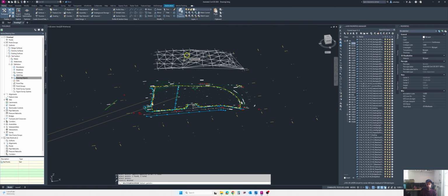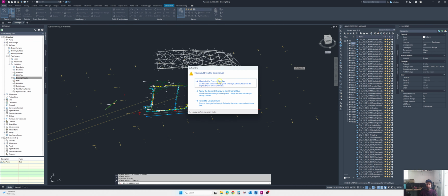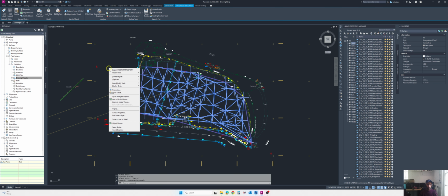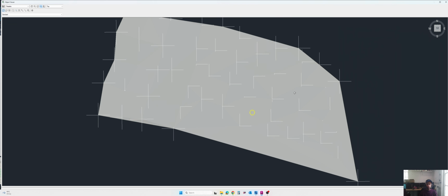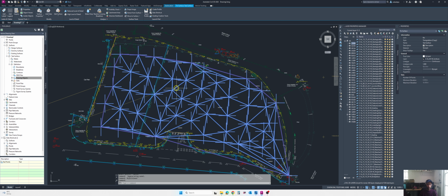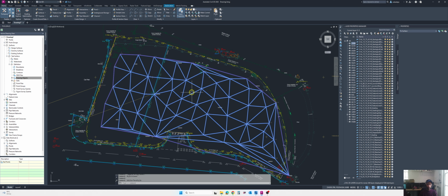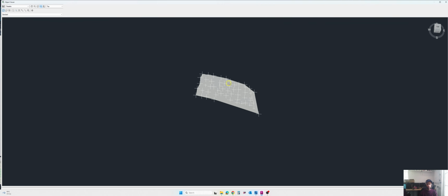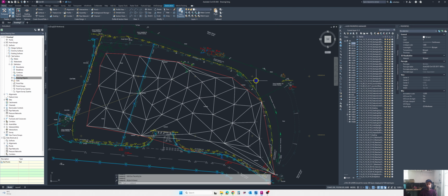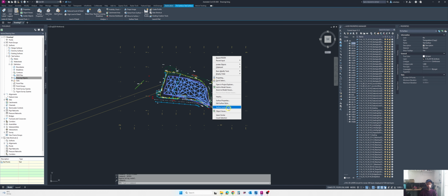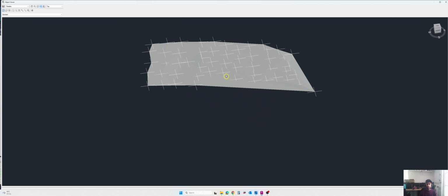and now you can see the surface has been put into the 3D plane while the rest of the drawing is in 2D plane. So press escape and maintain the current display and go top view. Now let's see object viewer. Let's just change our style to hide the points. And now in the object viewer, we can regenerate our drawing, and then it has now created our surfaces.